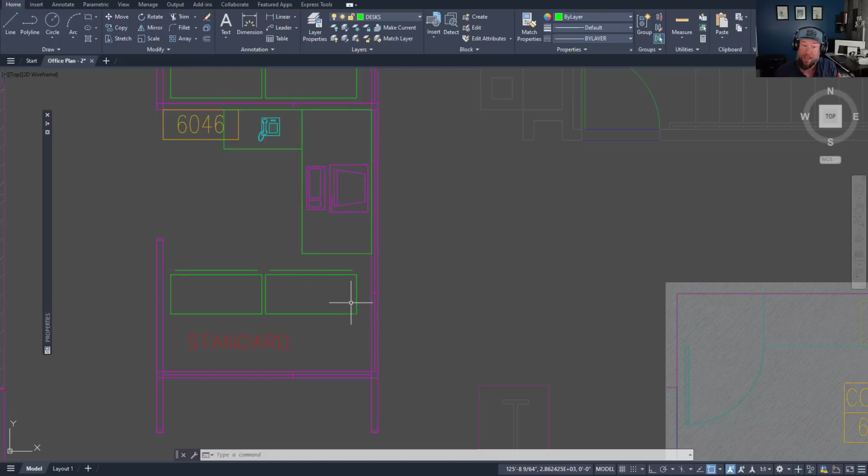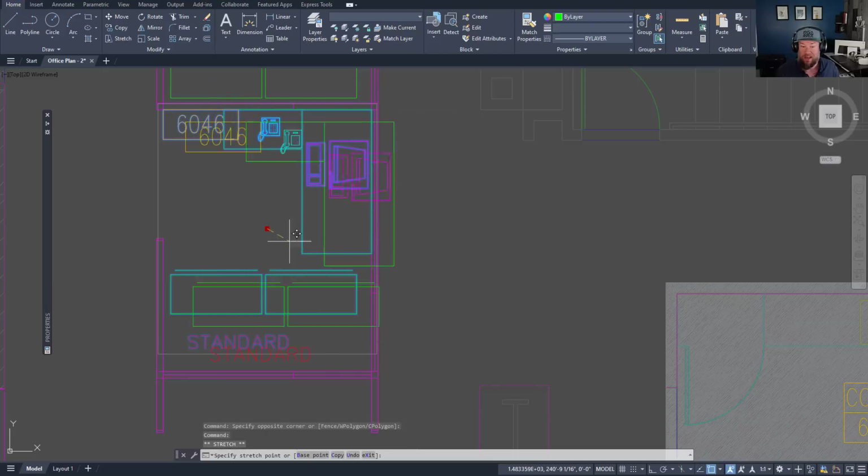Now comes that command. So if you hold down Control and tap H, you're actually just turning off the function of groups, but you're not breaking any of your groups. So you can see here, groups are deactivated because I hit Control and H, but I could just tap Control and H, and now groups are turned back on. So this is a great way to quickly move and adjust objects within your group. So I've turned it off. I'm going to move my computer over here. Now I've turned it back on. My group is now active again.